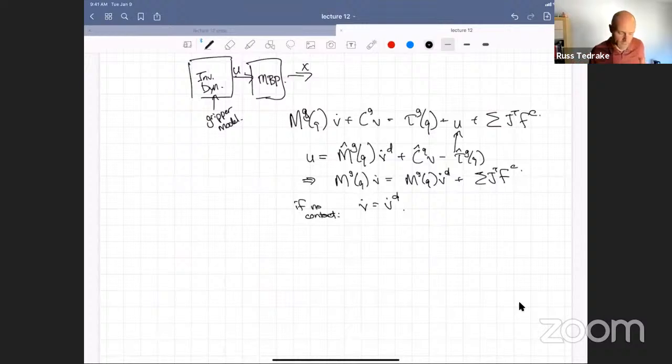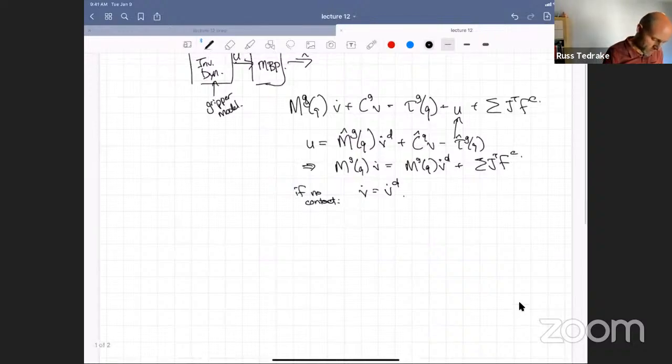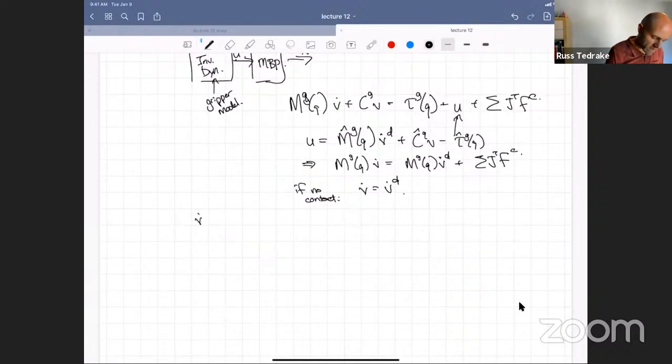If you had, in fact, the models that the KUKA is using internally in its controller to try to do something like this, not exactly this, we'll talk about exactly what it's doing probably Tuesday, but it is even trying to compensate friction terms. It has estimates of joint friction, and it will try to cancel those out too. Basically, take all of the cruft in your equations and try to cancel out everything you think you know and give yourself a simple set of equations. And then we say v dot desired is some PD controller, which is going to be like my Q desired minus Q, the ID controller, in fact.